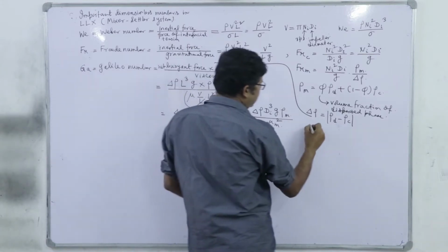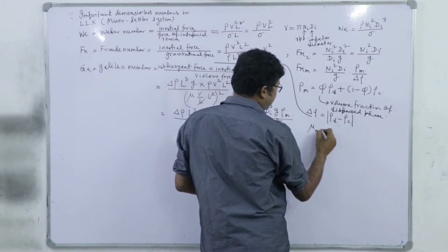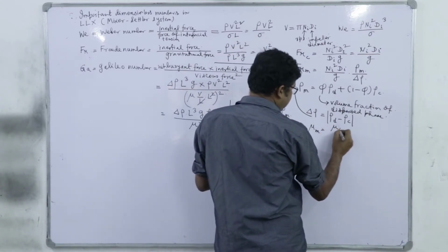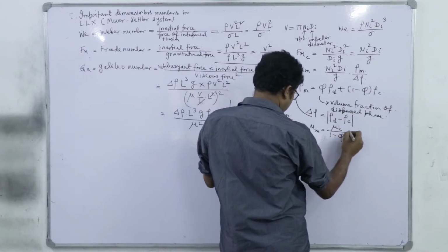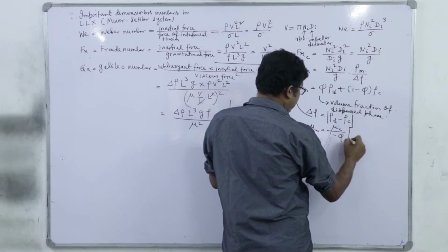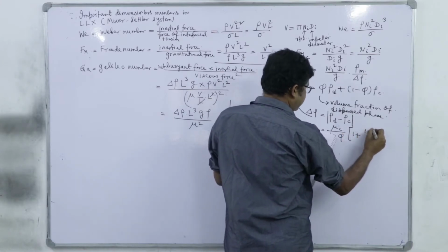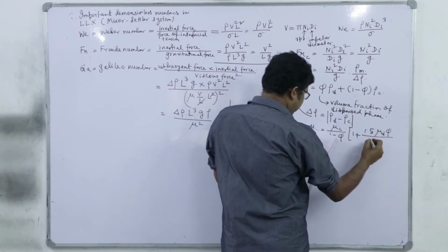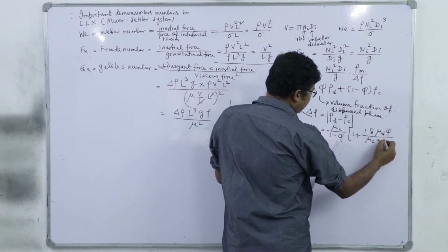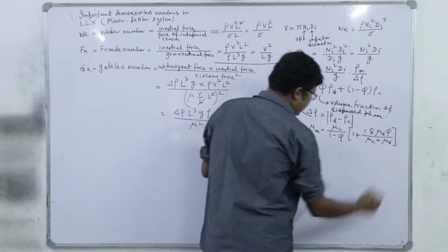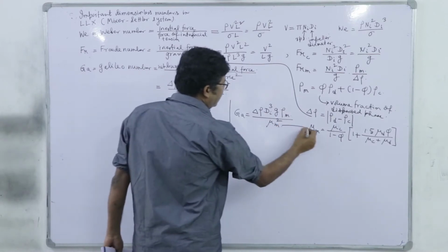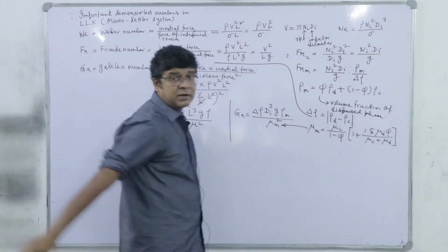So, mu mixture has an empirical rule by which we can calculate it. So, this is mu c divided by 1 minus phi. How we got it, we are not going into that. It is purely physical combined with statistical analysis, of what sort of average we should use in order to get the correct relation. So, this is the mu mixture, we have to substitute here, we do not have to remember this correlation.